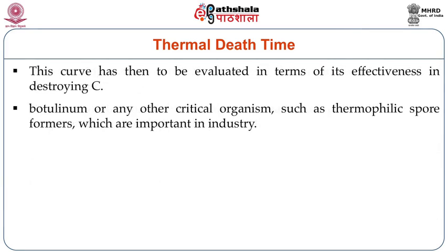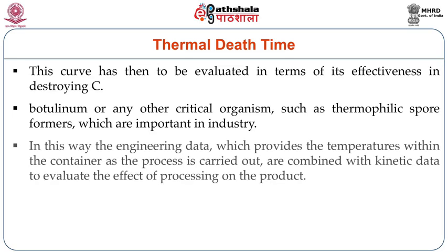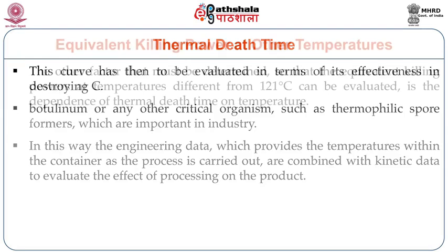This curve has to be evaluated in terms of its effectiveness in destroying Clostridium botulinum or any other critical microorganisms such as thermophilic spore formers, which are important in the food industry. In this way, the engineering data, which provides the temperatures within the container as the process is carried out, are combined with kinetic data to evaluate the effect of processing on the product.